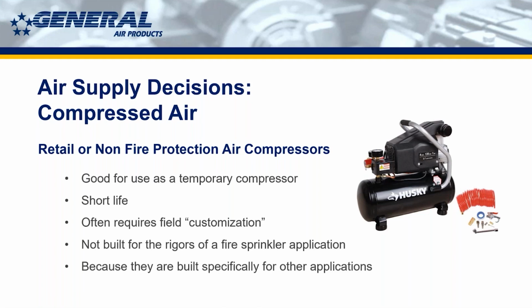I can't recommend enough not using these in permanent applications. For starters, they all usually come with handles or wheels or things like that. What the design of that unit is telling you is that it was not made to be permanently installed anywhere. They have a plug and cord, which is no longer allowed by the standard. They would go to a light switch, which is also not allowed by the standard anymore. Again, you can jump into our codes and standards webinars for that.